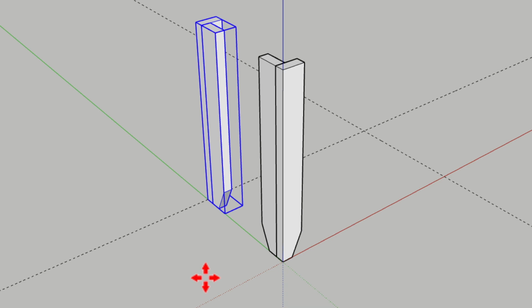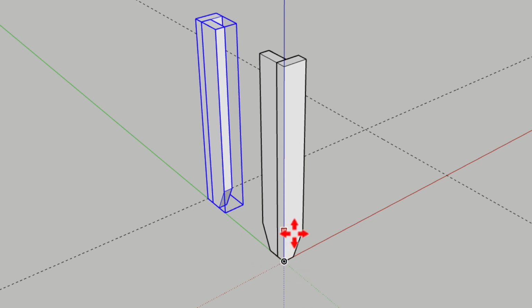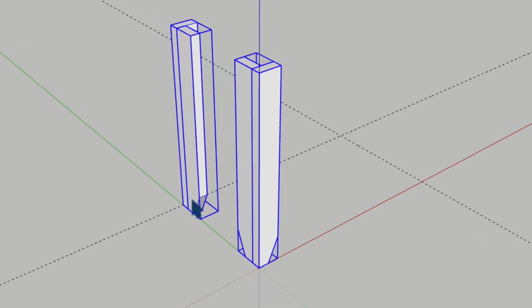Now we just need to select both of these objects. So you might say, which type of selection can I use? Well, if you wanted to use the crossing box, you would press the space bar. But if you go from lower right to upper left, you're crossing a guideline, and it selected the guideline also. Deselect by clicking on the right. We do have an opportunity to come up here into this area, click and drag, and just make a skinny rectangle, and that would select both as well. Remember, you can also use the Shift key.